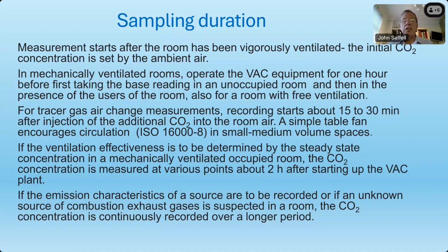We use human beings as our sources of CO2, and recording starts 15 to 30 minutes after injection of the additional CO2 into the room air. In this case, it can be no more than the fact that people have gone into the room and are occupying it. But if you don't know the number of people in there and whether they're leaving and coming in, you have a variable source, then you have additional problems in your calculation.